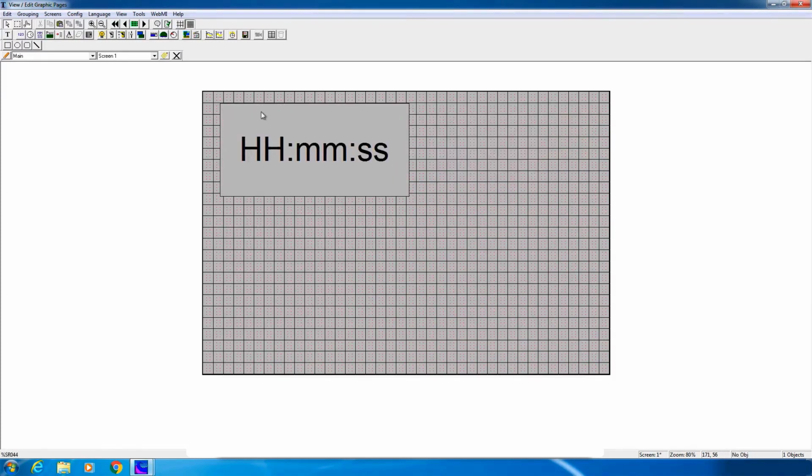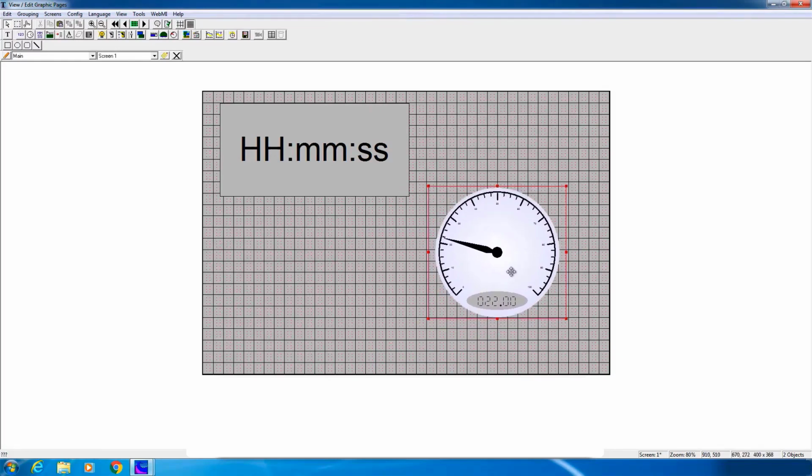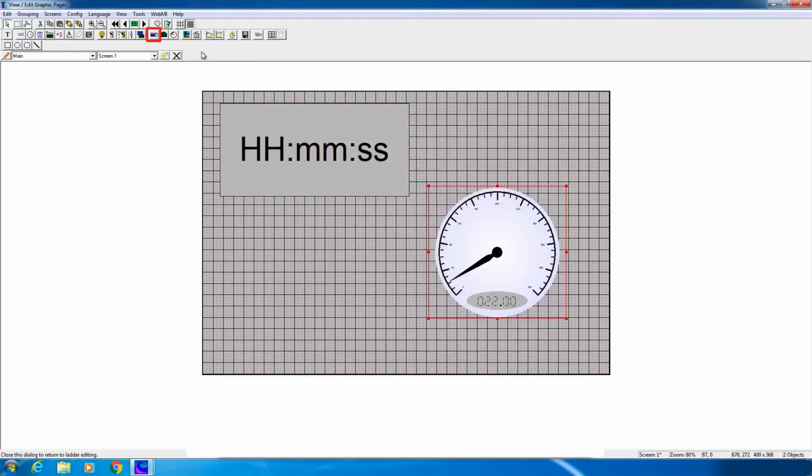Now, let's go ahead and pick out some data from the actual application. So we're going to create a new gauge object from this icon. This is where I can pick one of my existing variables. In this case, let's go ahead and select inlet pressure, inlet PSI, which is on my list. We know that's a scale from 0 to 400, so we've created a simple gauge. And we'll also create a bar graph as well. So let's make this one for tank pressure.